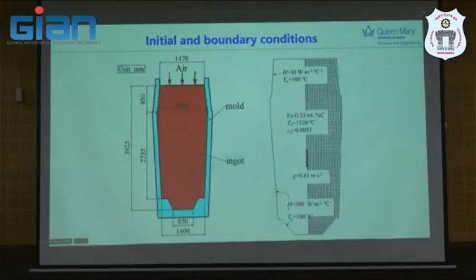May I add a little bit? So this is a large ingot of carbon steel here, and we want to understand the fluid flow during casting, because this fluid flow is the origin of the macro segregation. As you may imagine, the segregation is quite detrimental to the part. So we simulate thermo-solutal fluid flow, which means you get some dendritic growth, fluid flow, as well as the segregation profile.